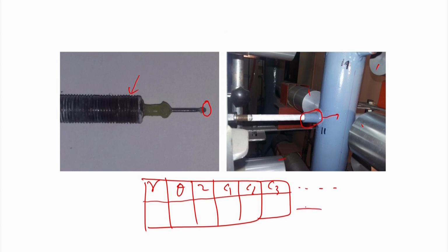So I will have a lookup table, which says how the detector counts are changing with the particle position. Okay, so this is called calibration. Then we perform the experiments, we get the time versus count, we compare the two and we calculate the position of the tracer particle.